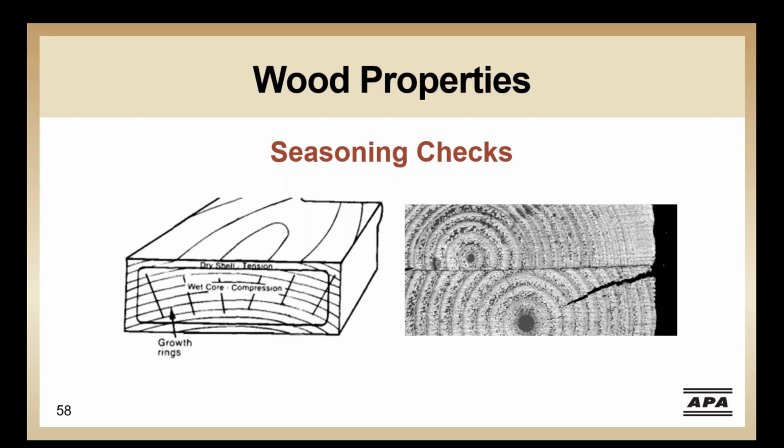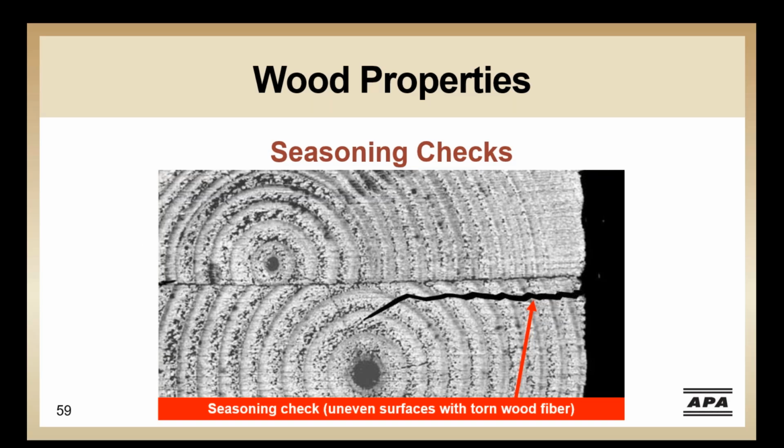Dimensional changes also need to be understood with respect to moisture changes. Exposure to weather and sun will increase the amount of checking in all wood products. Checks should not be confused with delamination. Wood lamination and glulam have moisture contents limited to 16% and are typically well below this value at the time of manufacture, which results in fewer seasoning checks.